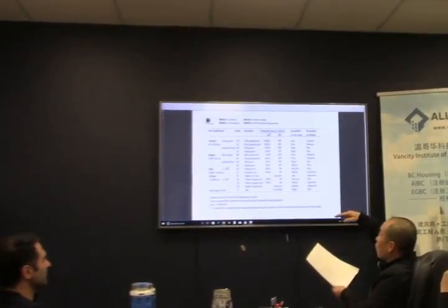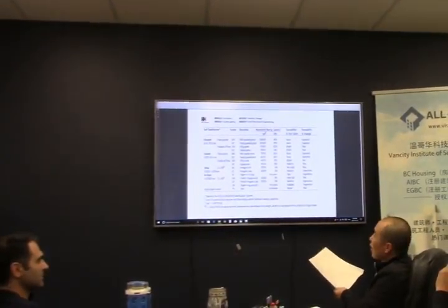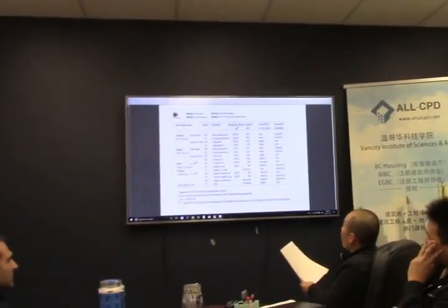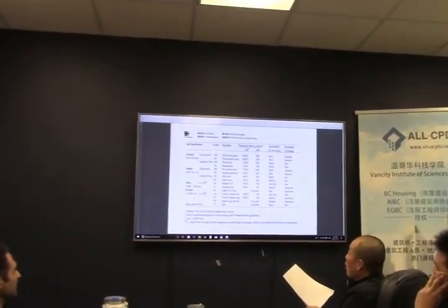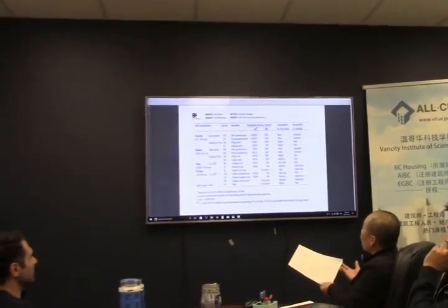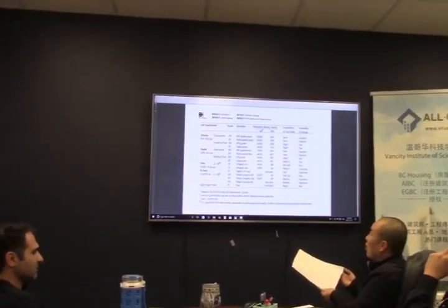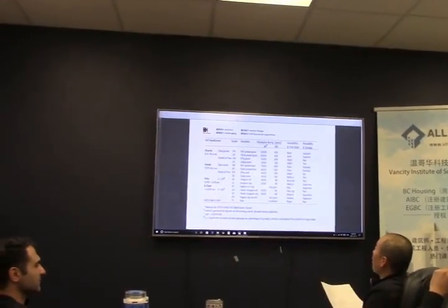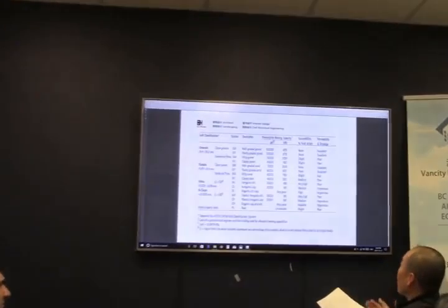After gravel is sand. Sand size is 0.05 to 6 mm. And for sand, the bearing capacity is less than gravel, about half the gravel's bearing capacity. For frost action it is almost the same, slight. Because they have a smaller size, they have some water inside, the water ratio, so they have a slight action to the frost.